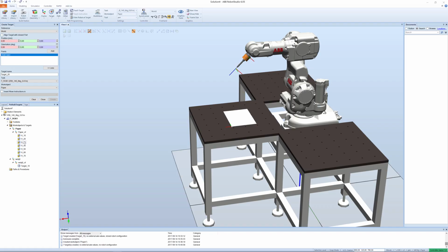And what we do now is just to check that we can walk through, but first we have to actually create the path. We right click, create path, right click, left click on that one, and we call it path underscore H, like that one. Now we start with the home position, target 10, drag it down to that one, open up.